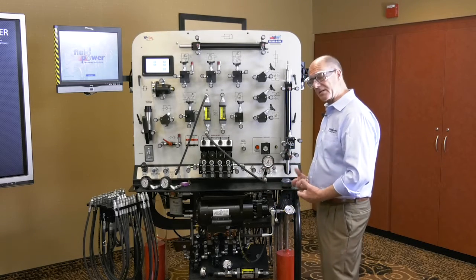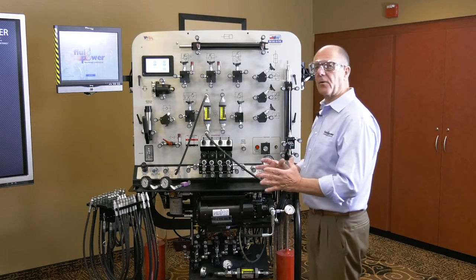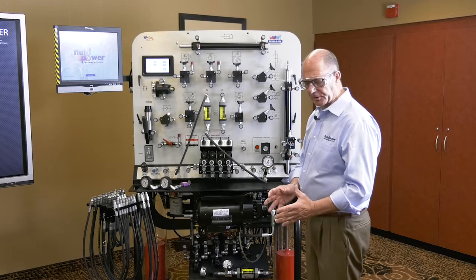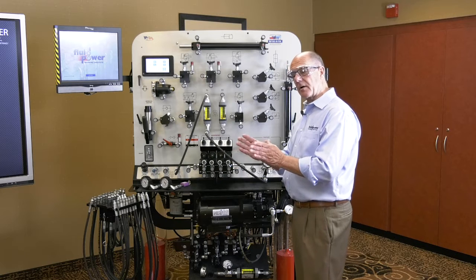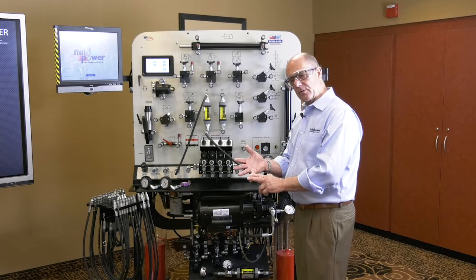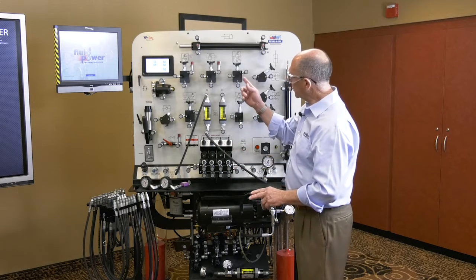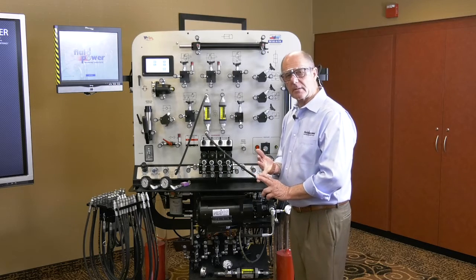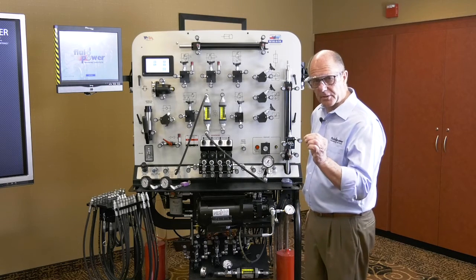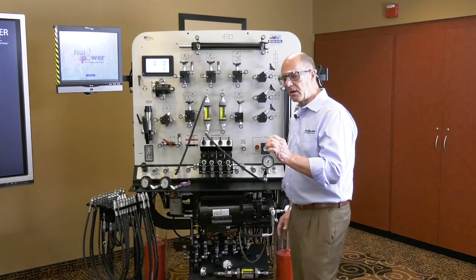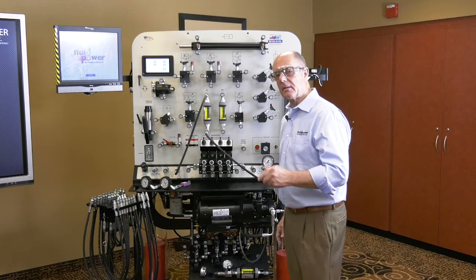In other words, from a design point of view, I have established that I am within the 4 inches of mercury recommended by the pump manufacturer. For the consumption of people that maintain the hydraulic system, I've got to make sure that at this altitude, about 4,600 feet above sea level, and at this temperature, which again is about 68 degrees Fahrenheit, the inlet restriction point of reference for this pump is 3 inches of mercury. And that is a vital operating parameter which needs to be monitored on a routine maintenance basis. Let me explain.